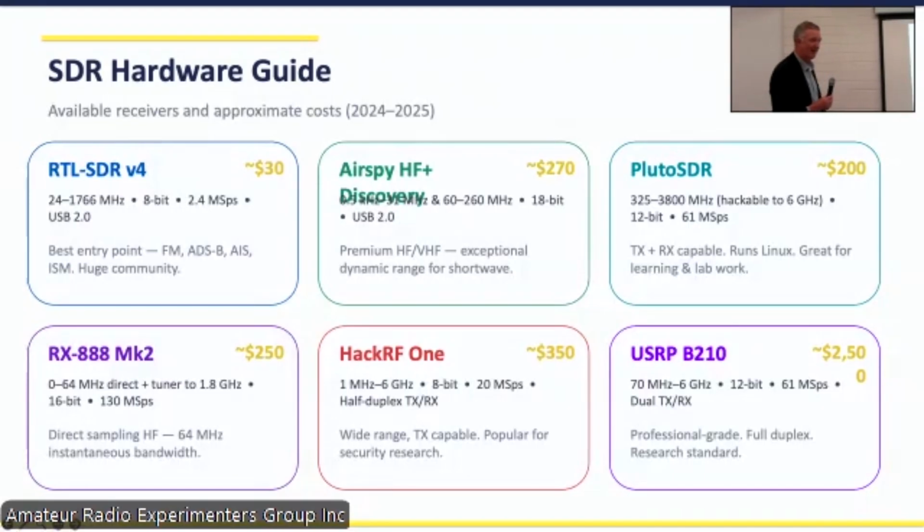Even though it's low power, a good example of that is the GPS frequency. You look at the regulations, the maximum you're allowed to transmit there is minus 73 dBm. It puts out quite a bit more than that. And you do not want to be involved in transmitting on those frequencies and getting caught.